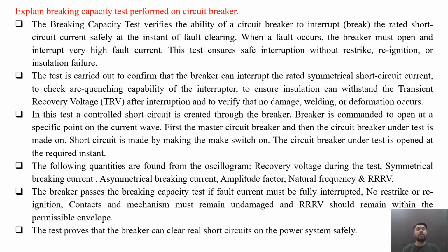The test is carried out to confirm that the breaker can interrupt the rated symmetrical short circuit current, to check the arc quenching capability of the interrupter, to ensure insulation can withstand the transient recovery voltage, that is TRV, after the interruption, and to verify that no damage, welding, or deformation occurs.